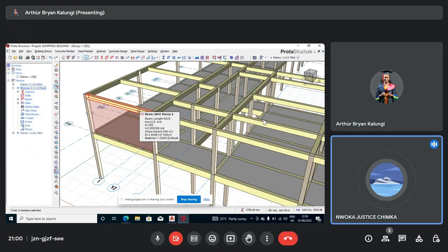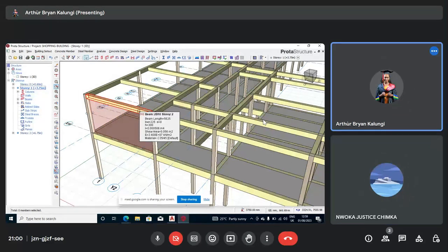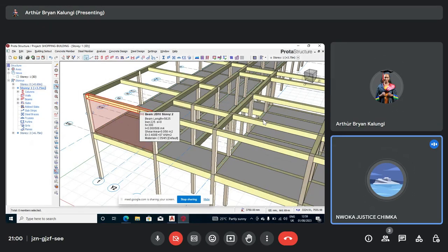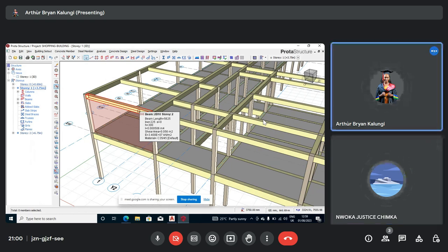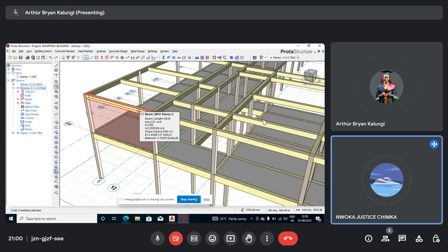If you put your block wall load on story 2, you will see that it will be going up to the roof, which is not correct. So always put your block wall load beneath the beam, not the one above. Except you have up to 2 stories, then you can put another block wall load again on the next story. So right now, let us click on story 1 beam. Make your story, yes. Then click there, drop it down.